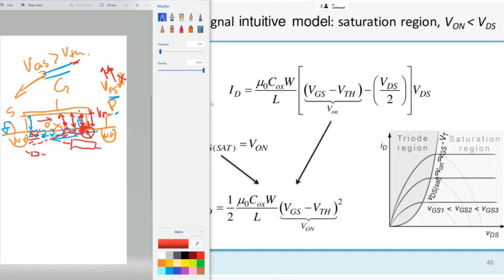Of course, I will not follow the equation, because I cannot create negative charge densities. Physically, the charge density is just zero. So I saturate at zero. Then this means that the channel resistivity or conductivity will saturate to a certain value.